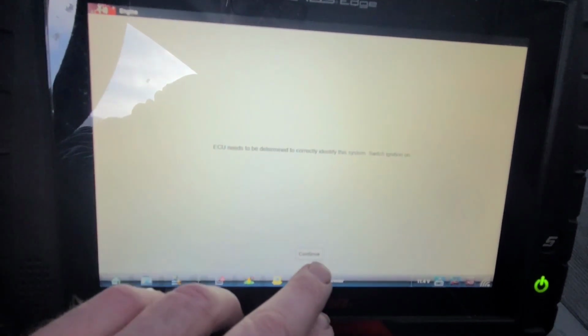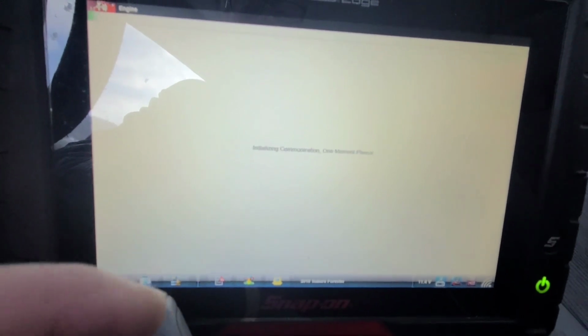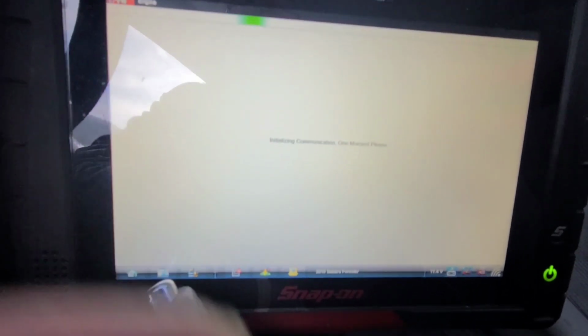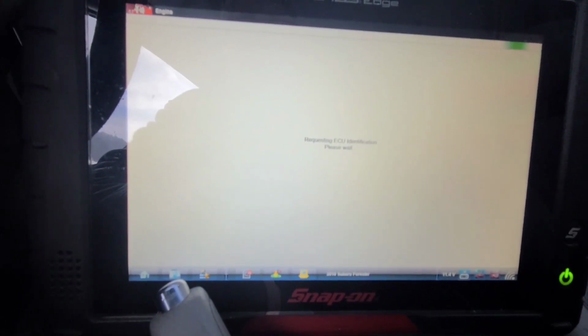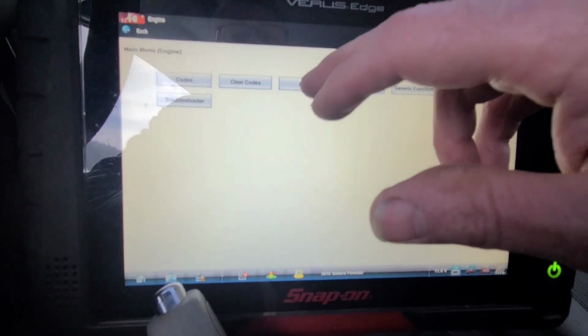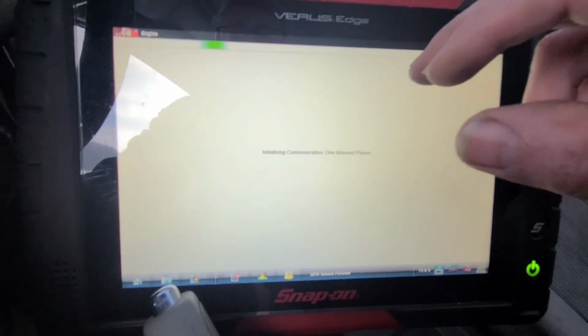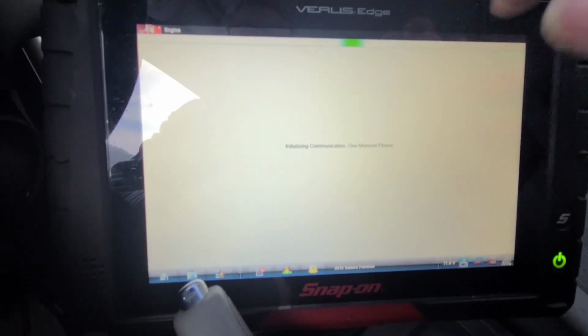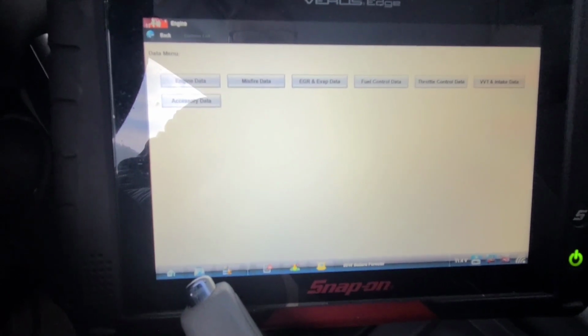Record the temperatures during cranking, injector pulse width. The last 3 days it's been fairly mild and it's been starting, although the last time it was a little longer than I would have appreciated for cranking.